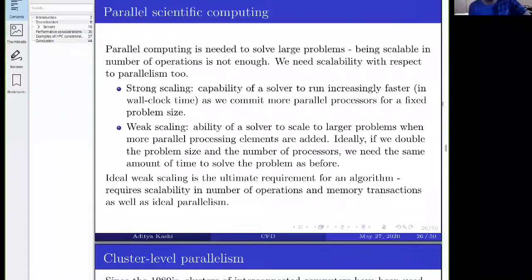For example, there are discontinuous Galerkin methods, which are quite suitable for compressible flow problems, but they are more complex to develop and have more issues to develop. Whereas the continuous finite element methods, which are more typical, may not work as well for compressible flow problems, though again, they have also been used. So it's quite a rich field, and there's no short answer to this.